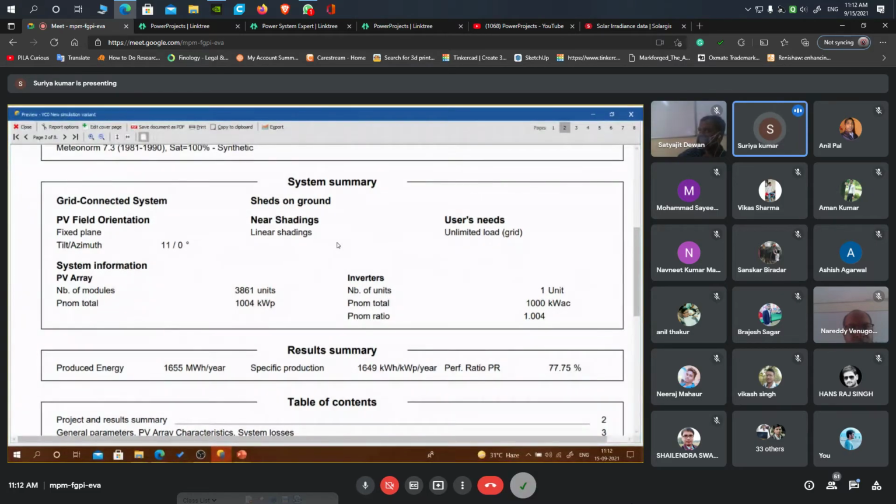One behind one, same like that. Here also your panels will be placed one behind one, so the first panel's shading may fall on the second panel, depending on the sun path, so we can include that here, right? That is the linear shading which I am specifying here, depending on the module layout as well. I can define that, right? That and all is given here. And how many modules I am going to use in this plant.